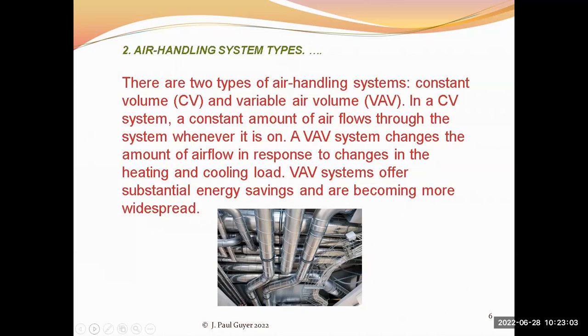And so if it's getting too cold in the space, the thermostat tells this VAV box to close down and reduce the volume of air being discharged into the space. And then vice versa, if it's getting too hot, the thermostat tells the VAV box to open up and put more air into this space.